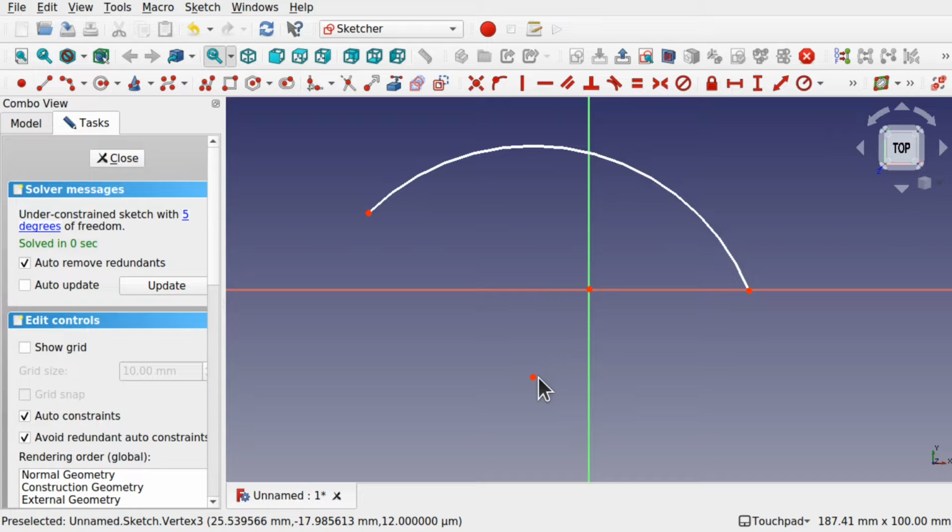Now the trouble is that we can't use a formula because we've got two different measurements in there. We've got a degree and we've got a millimeter or inch, so the unit differs. So we have to use a spreadsheet. I'm going to calculate the radius. So what radius do we need if we have an arc length of, say, 150 and an angle of, say, 90 degrees? The formula you want to be using is: the arc length will equal the radius times the angle.